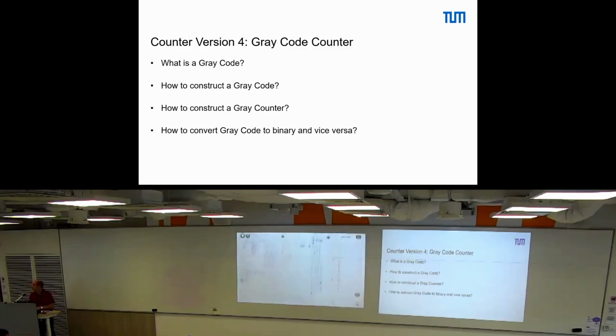This is always a signal G. And we have a binary signal, we call this B, with 3, 2, 1, 0. Now, obviously, G3 and B3 are the same. So if we want to translate G3 into B3, we can just forward it directly.